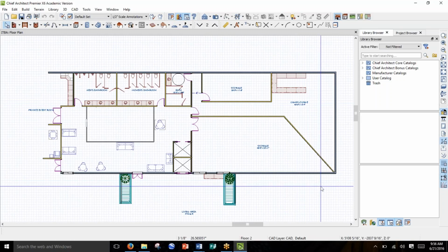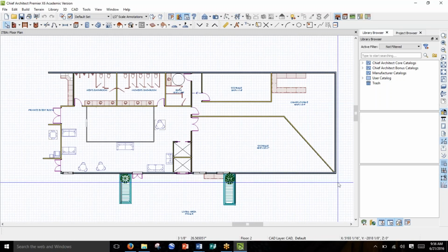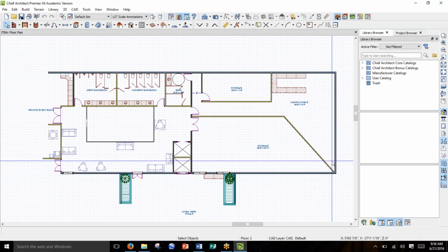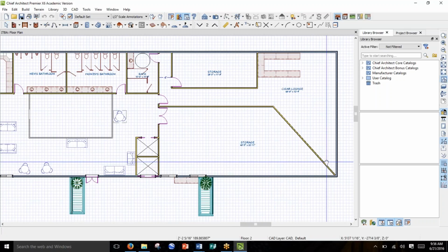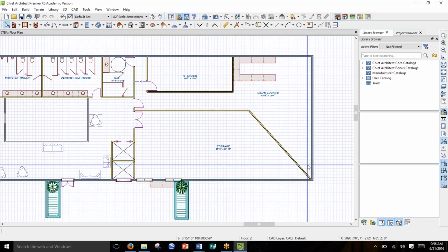And then let's see. I'll just have to know when you're thinking about the egress. According to our book, you would start from the lowest part on the right of that triangle. I'm assuming there'll be some seating within that area, but really that could be the point that the person is farthest back in that room. For some reason, they're facing the corner in the back. So they need to escape from there, and that's where you start measuring your footage.